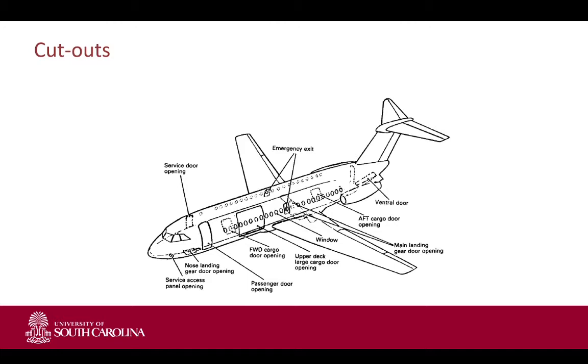Because if you take out a panel, then the forces will be redistributed. We can assume that they get redistributed as shear flows in adjacent panels, or we can assume that the stiffeners take up all the normal forces, and the panels take up the shear flows.